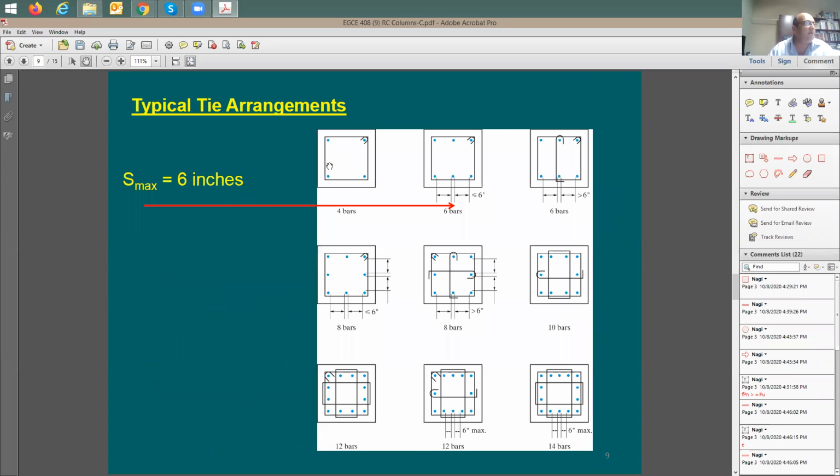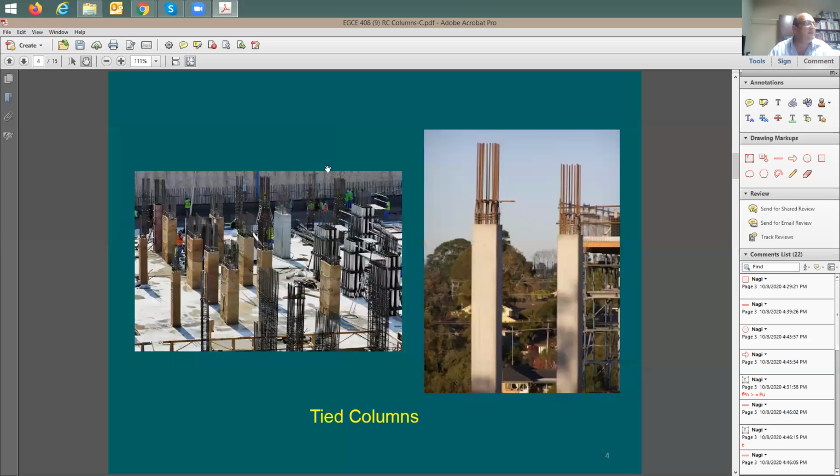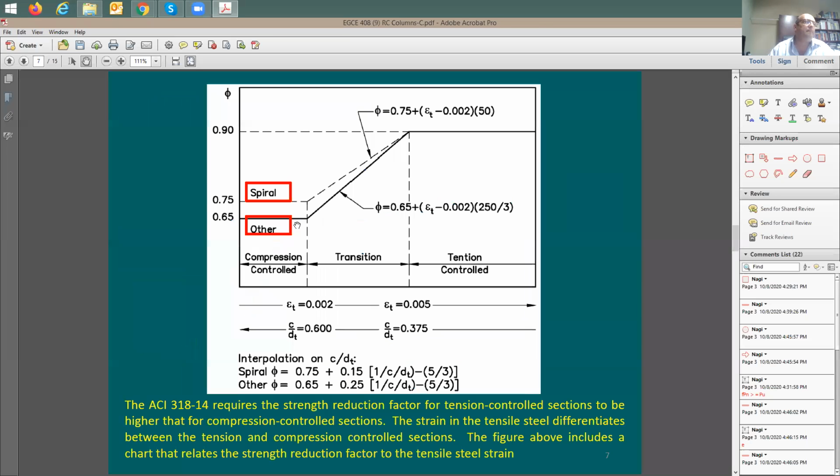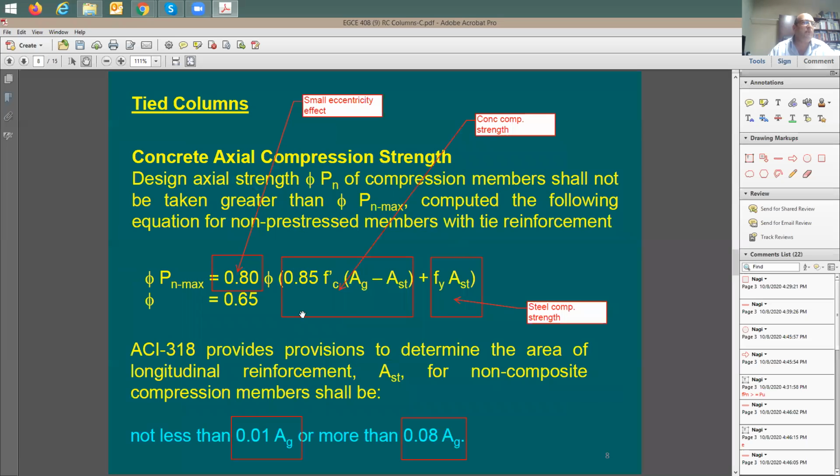So when you have any vertical load, I'm going to go back here a few slides. I marked this before. I said if you have this axial column load, and you have some eccentricity, it means that you're going to have this axial load plus additional moment coming this way. It's going to be clockwise in this case. It means that your column here is exposed to axial load and moment. But as long as this eccentricity, I'm going to call it a small eccentricity, I don't really need to check the moment applied on the top of the column. I will just take the axial column load capacity. Meaning, again, this equation here does not consider the effect of moment applied to the column with the axial load.